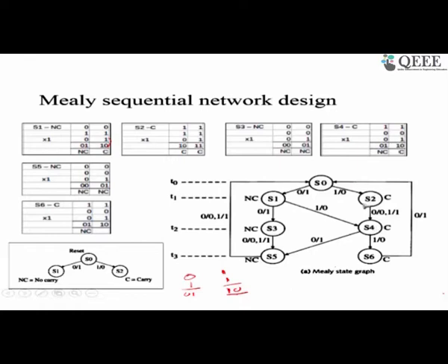Similarly, S2, if you take that one, S2 is a carry state. So we remember carry, so a carry bit has to be added and a 1 needs to be added because it is the second bit in XS3 conversion, a 1 needs to be added, but the bit x1 can be 0 or 1. Accordingly, these 2 are the possibilities. So here we have 1 1 0, which means on addition you will get a 1 0. Here we got 1 1. So what we do is, on getting 0 we produce 0 and go to a carry state.